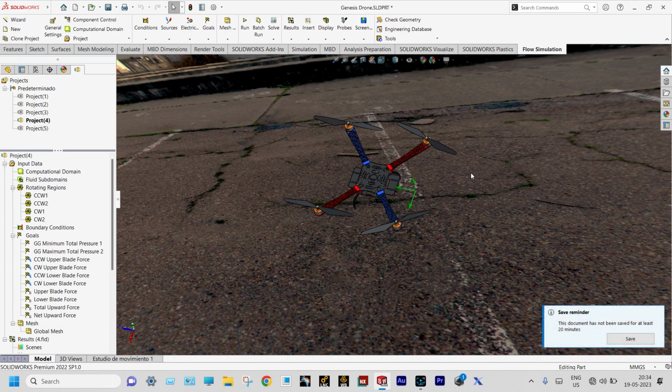And finally, at fourth experiment, we could see that when the RPM is 6000, in that case also, the net thrust is positive. So from this analysis, it is evident that we should have a better control of the angular velocities of the propellers to control the drone. Because if we are trying to move the drone in the upward direction, in that case, angular velocity of all the propellers will be same. But if we want to move the drone in the backside or front side, in that case, the RPM of the rotor should be varied, right? Okay. So with this one, we will conclude our today's analysis.